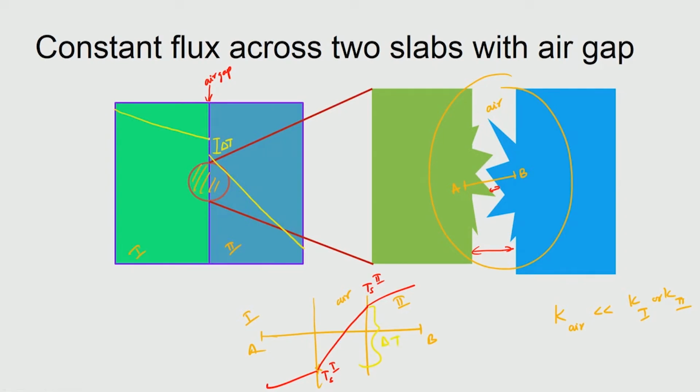Okay. Now, which means that when you look at the heat that is going in this direction and this direction, it has to go through this gap, which actually should also be modeled. So, we then write an additional term here. So, this heat that is going through the bulk up to the interface would then be proportional to K1 delta T1 by delta X1, but the interface resistance is then modeled as H into delta T, and then in the other wall again from here it would be K into delta T2 by delta X2.